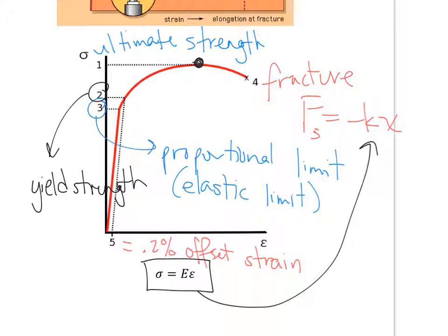So here's your stress-strain curve. Before we go further, look. As more stress is applied, proportionally, it stretches more. In this region, it follows Hooke's law. It's acting like a spring. If we stopped right now and removed the specimen, it would go back to its shape because it hasn't reached that curved part where it starts to yield and become what's called plastic deformation, like a plastic bag. That's the term.